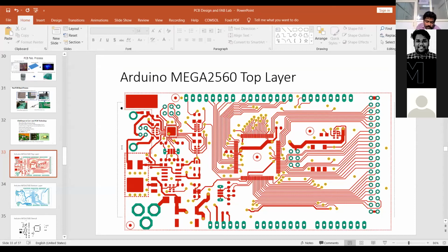Again, what really happens is it will not clearly remove the material when the spacing is very small, because the resolution will not be very good. You will get, for example, less than 0.3 mm or near 0.3 mm. It's very difficult to attain unless you have a very good quality prototyper, which will be very expensive. So that also needs to be considered when you go for PCB design.